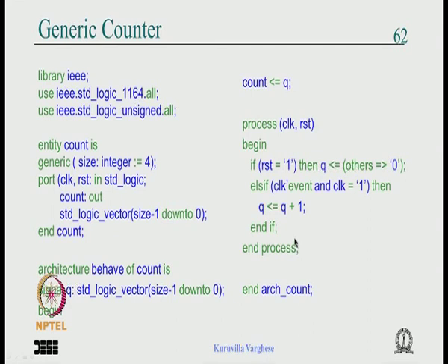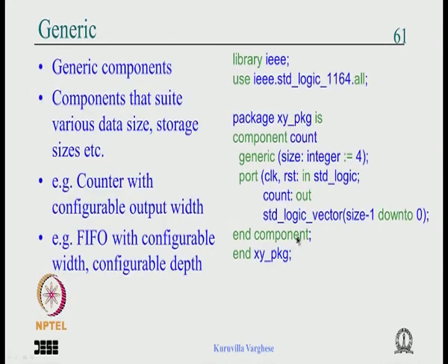Since we are putting this into a package, we write a component package header with the library and the 1164 package use clause.